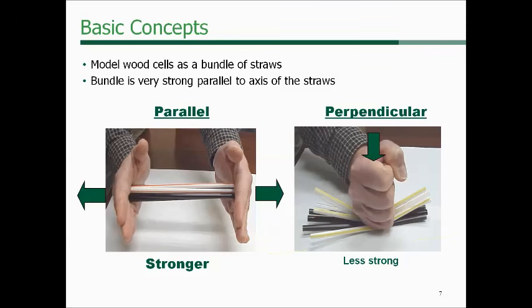And there are reasons for that, and that gets into wood science, which we won't do here today, but it has to do with the way those fibers are bonded together. And so we're going to avoid situations as much as possible in connection design that would create tension perpendicular to grain stresses, and try and get more bearing on the wood members.